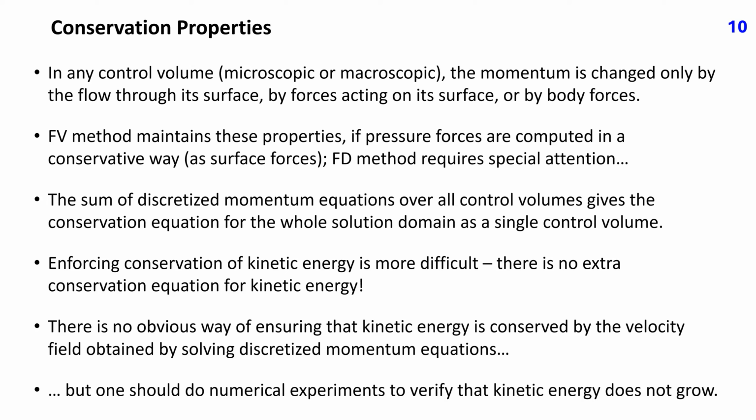It is derived by multiplying the momentum equation by velocity. Therefore, there is no obvious way of ensuring that kinetic energy is conserved by the velocity field obtained by solving discretized momentum equations. However, one should do numerical experiments to verify that the employed discretization method does not cause a growth of kinetic energy with time when it is physically not supposed to grow. One such numerical test will be presented in lectures 19 and 20.